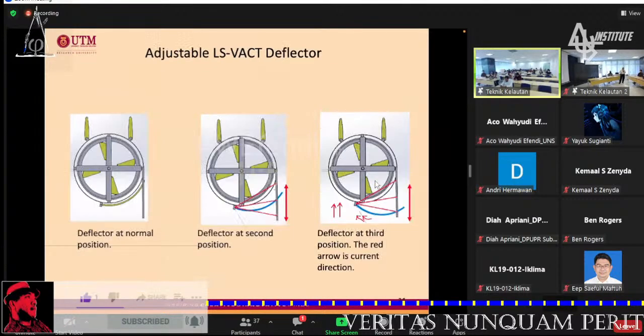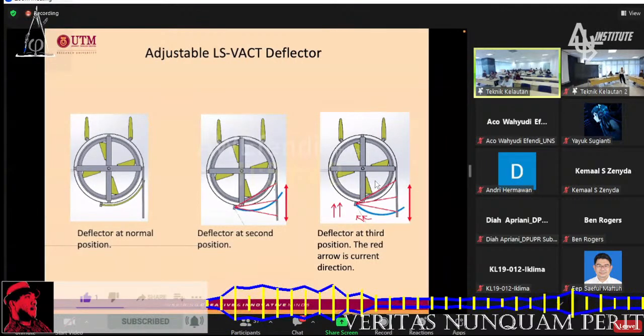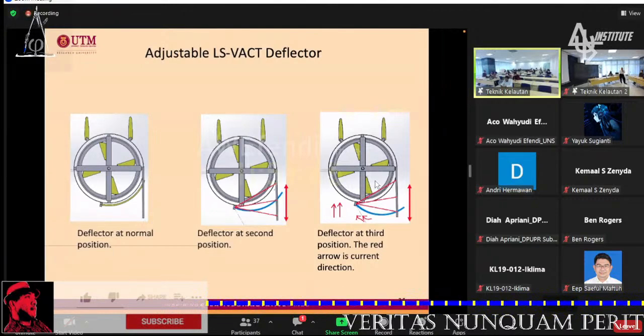Okay. So this is just showing you the mechanism of how you get the energy. We have the plate here, and we also call it the deflector. So we can deflect the flow from here to this side, so that we can improve the torque of the turbine. And also because the current is a tidal current going back and forth, we put a rudder so that it always points towards the incoming current. But this is maybe not practical, maybe you have to think of something else.